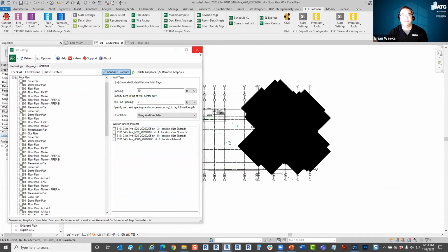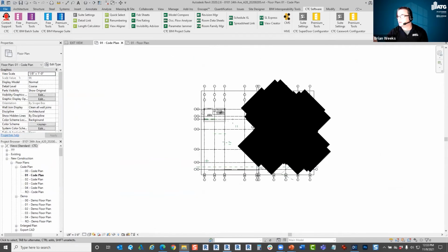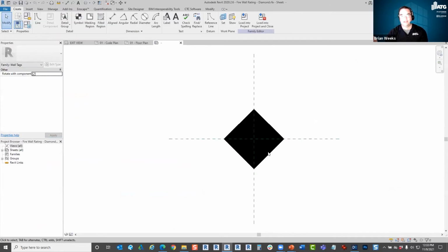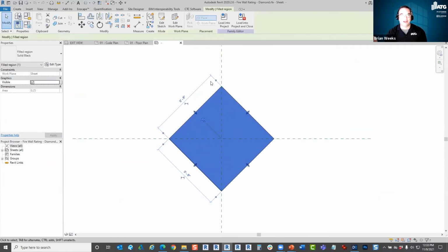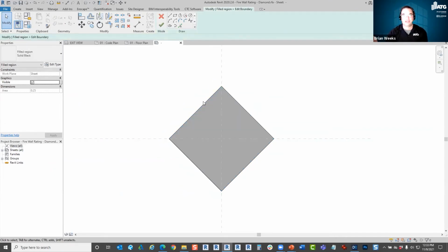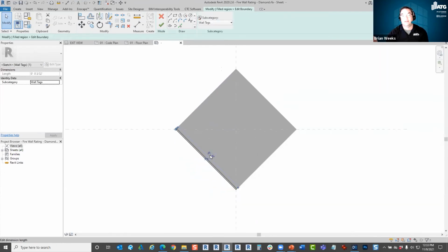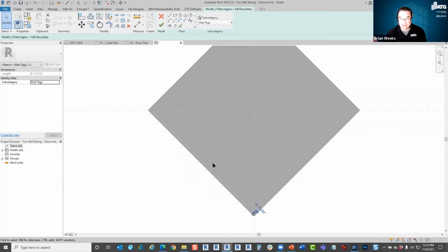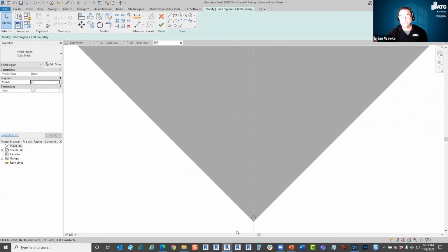I think I accidentally created the wrong family. So give me just a second. Oh yeah, this is still my old one. I apologize. So you're going to get to see me fix this real quick, because I wanted it to be a 6-inch graphic. And when I started messing with this, I was like, oh, well, that's really not what it needs to be because it's an annotation. So we have to kind of go back to this annotation type setting. So it needs to be a 3/32.